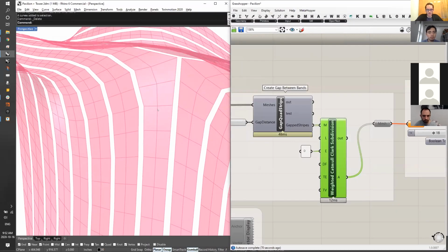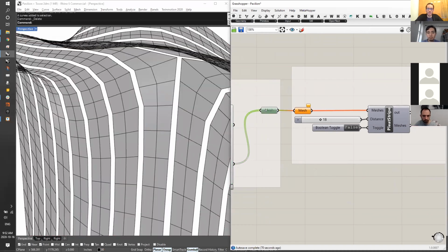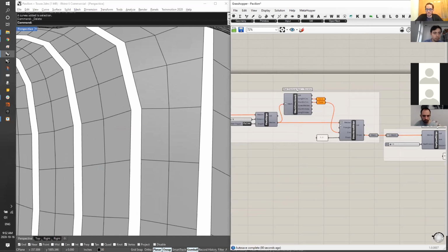We're taking that center line that's running through, and we are lifting up what's called the non-naked vertices. Naked being any vertex that's exposed to the edge, non-naked being any vertex that's sitting inside the mesh, that has no exterior exposure. So let's go ahead and see what that looks like.